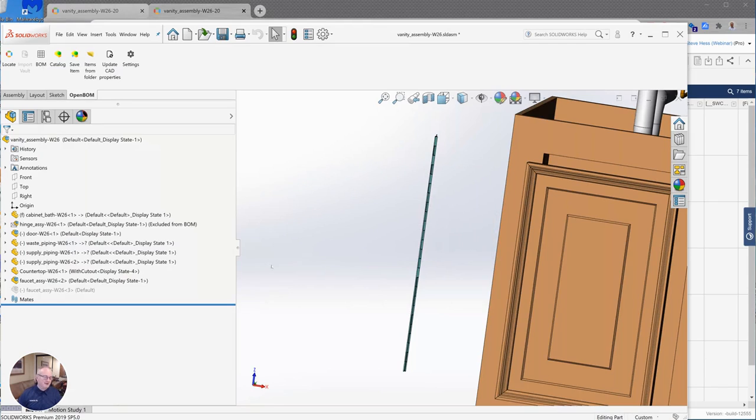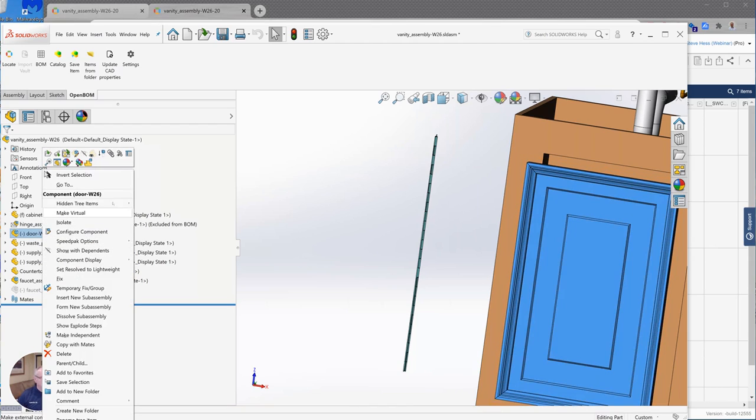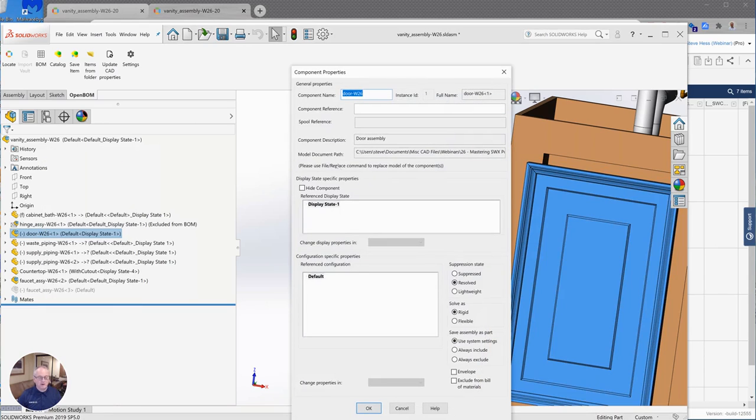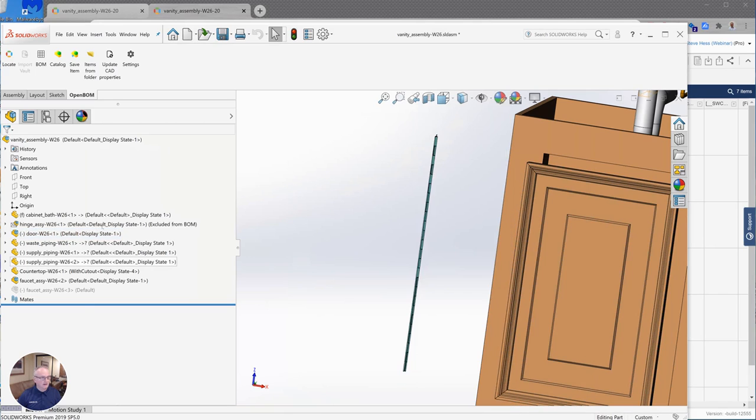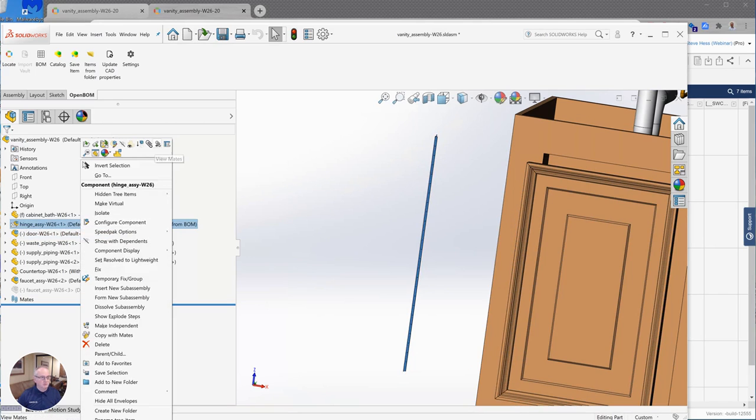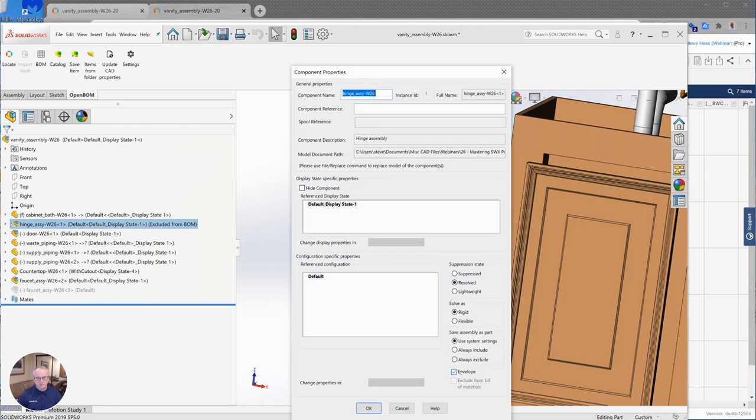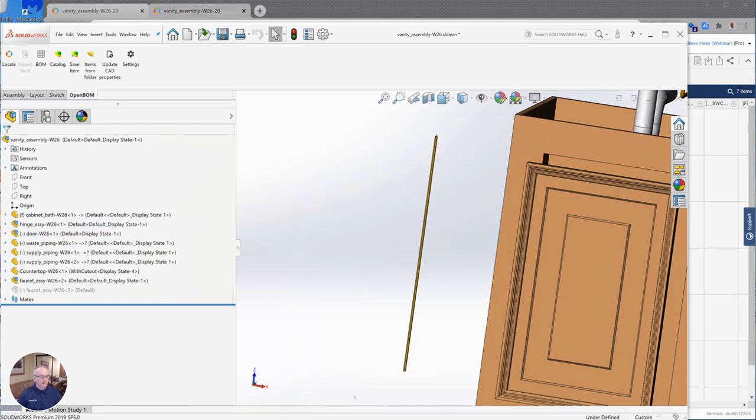But what that means is every time I use this hinge assembly in some other assembly, I have to go through this setting it to envelope. So let's look at a better, more permanent way to set that. So I'm going to make sure that I've got envelope turned off. Let's go back here and uncheck envelope. And so now let's open up this assembly.